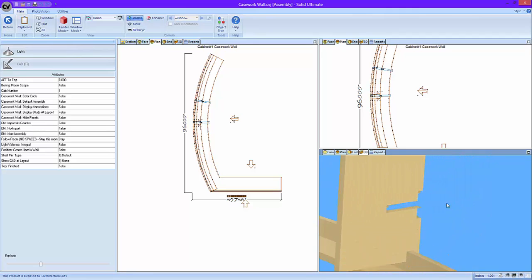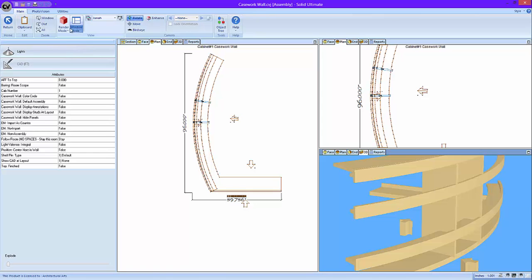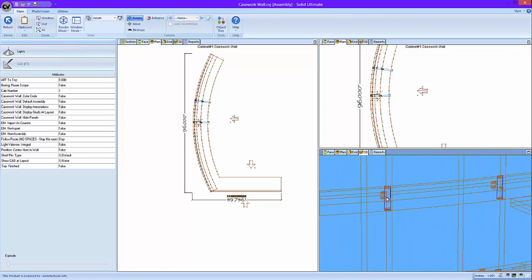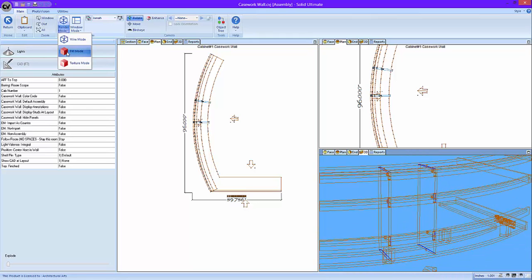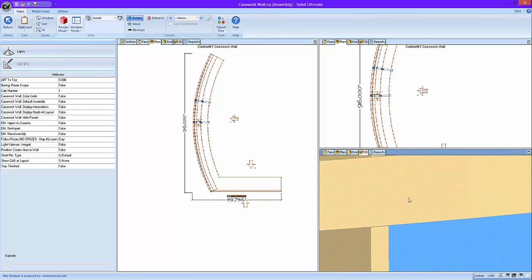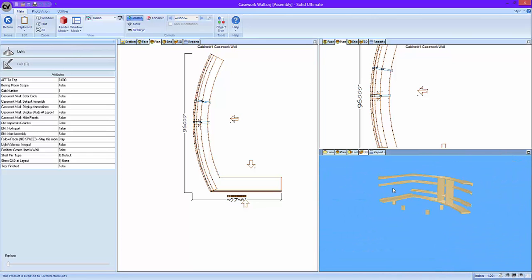I didn't mention this before, but all of the stud notches use a line bore to ensure a perfectly square corner, and all of the parts are sized to fit with a little bit of tolerance inside of where they go. As you can see here, it even adds a line bore for a screw hole into the standing cleat on a radius, which is pretty cool. Everything else basically works the same here, so nothing special there.